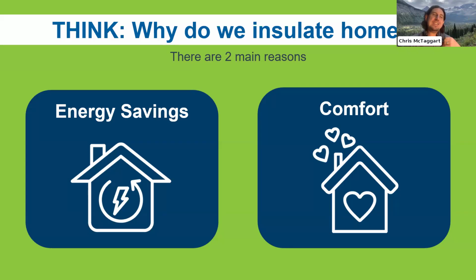It's not necessarily draftiness like wind blowing in. It could be, but usually it's actually the feeling of heat being sucked off our bodies and radiated into that uninsulated glass assembly. Same thing if we have poorly insulated walls or a poorly insulated attic or poorly insulated basement walls. It's not going to feel as comfortable as if we had a fully insulated building enclosure.